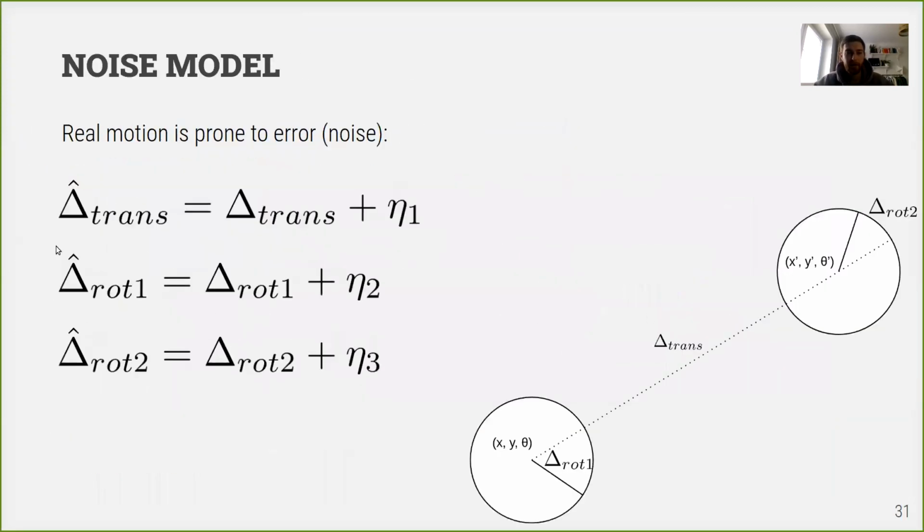And here, we just use the estimated, for example, travel distance, and we sample from the distribution and add random noise here. So in practice, it means that knowing from encoders that our robot traveled, for instance, 1 meter forward, even though encoders are saying we traveled 1 meter, we know that there is some noise, and to account for this noise, we will just add some random variable to our estimated travel distance, and we will have some distribution.